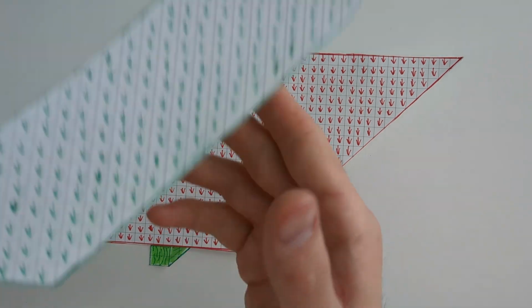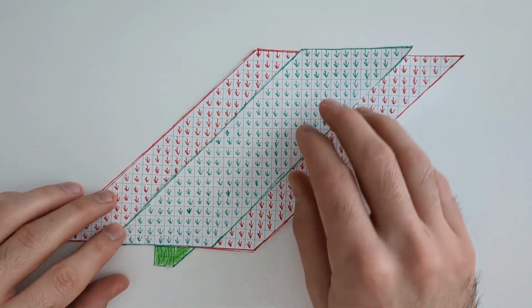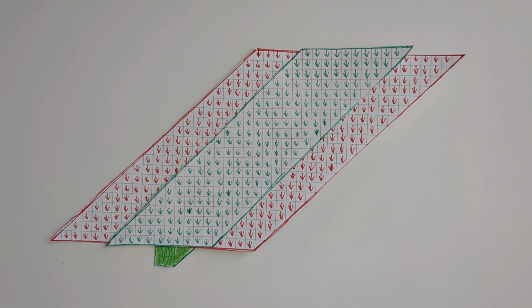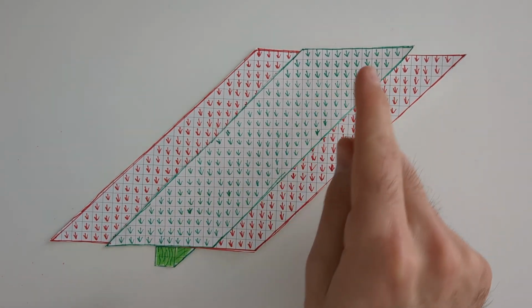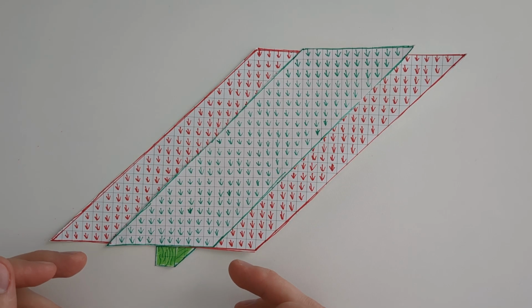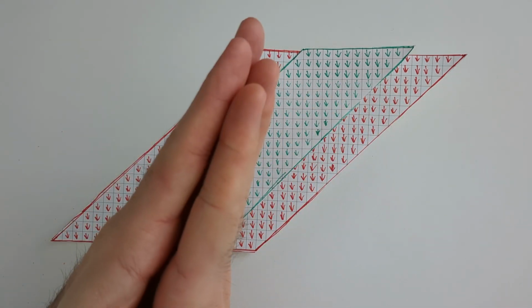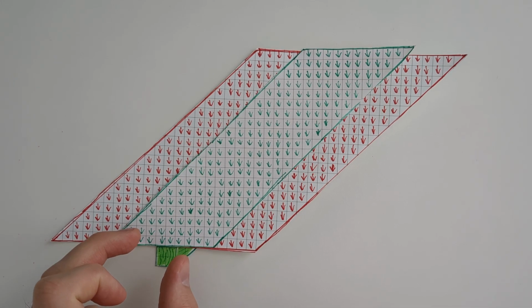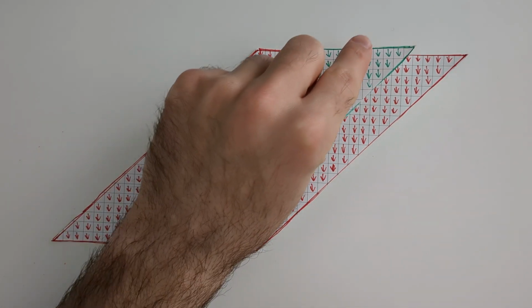So let's put our tributary area on top. Now, as we learned, the length of our tributary area is 10 feet. In order to determine the linear load on the beam, all we have to do is somehow get all of the pressure acting in this area into a linear load along the beam. And what we can do is we can compress this pressure until we get it into a line that aligns perfectly along our beam.